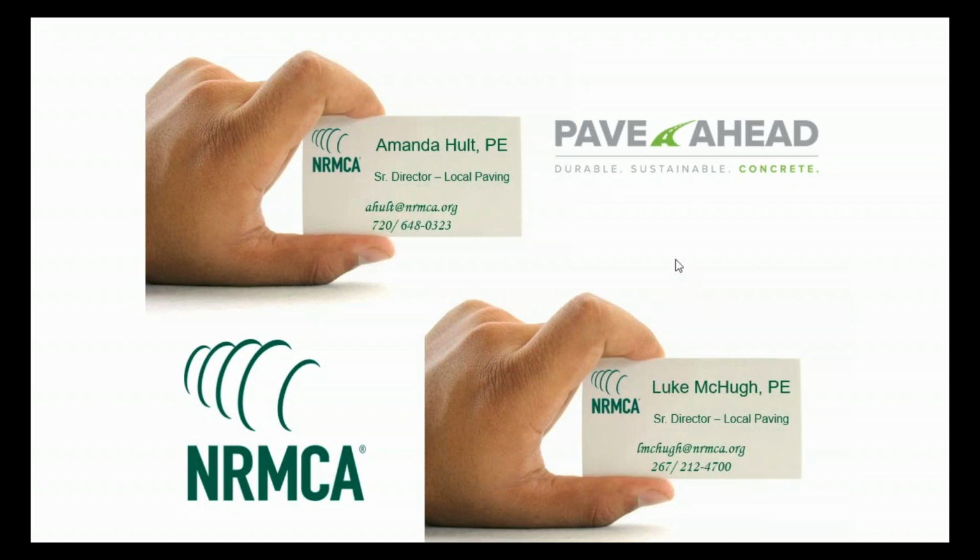Yeah, so there are potential issues with curing, especially in very large placements. You've got to be very smart about how you lay out what you're doing, particularly with the type of equipment that you're using, whether it's a laser type screed or formed placement or whatever. There are a lot of different ways in which you need to make sure that you get the curing done properly. And if you don't, then you can end up with some performance problems. So one of the ways to get around that is to utilize lightweight aggregate and internal curing.